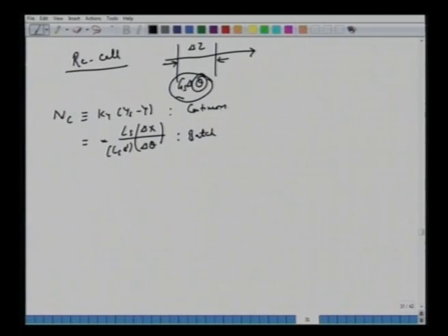In the case of mass transfer, we wrote Ky (Ys minus y) and equated this to Ls del x del theta with Ls a prime. You should go back to the previous lecture and see how we obtained the expressions for the mass transfer coefficient. Similarly, based on this, we integrated and wrote theta, how long it will take, as Gs over Ky Ss a prime times ln of (Ys minus y2) over (Ys minus y1). So this was derived for the mass transfer aspect.